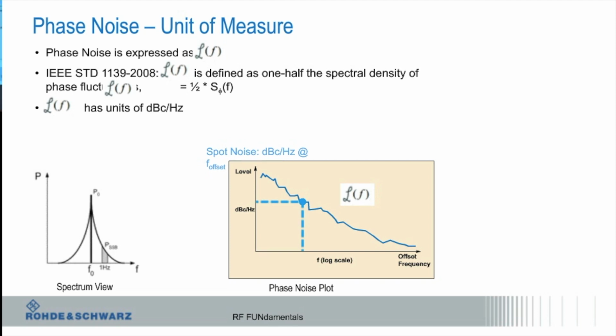Yeah, basically. If the spectrum analyzer's bandwidth filter is 10 hertz wide, what I'm wondering is whether it's narrow enough to be able to actually see. It depends on how good the oscillator is. But if you look at a typical oscillator and get really in close, it might be only 50 dBc down. So you easily can measure that.